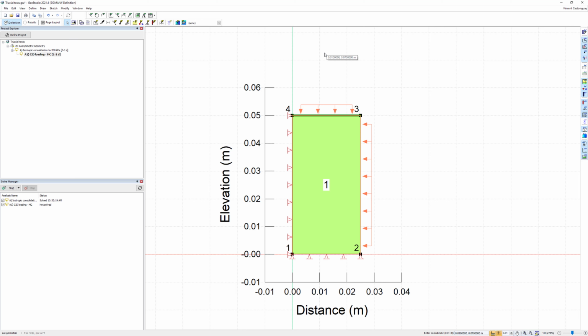This subtlety is very important to grasp and represents a common mistake we see our users make. As we have indicated, when defining the analysis, the stresses from the consolidation parent are inherited by the triaxial loading analysis. This means that the stresses already exist within the domain. If we leave the normal stress boundary conditions as they currently are for this analysis, we would be applying once again the stresses upon solving. Let us verify this statement with a quick test.